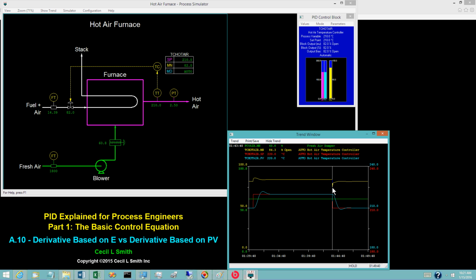The pulse raises two issues. First, only rapidly responding final control elements will propagate the spike or pulse to the process. Second, concerns regarding wear and tear arise for final control elements of a mechanical nature, such as control valves. In practice, the difference in performance is too small to offset the consequences of the spike or pulse. The difference in behavior only applies to changes in the set point. Performance for disturbances such as the fresh airflow is exactly the same.